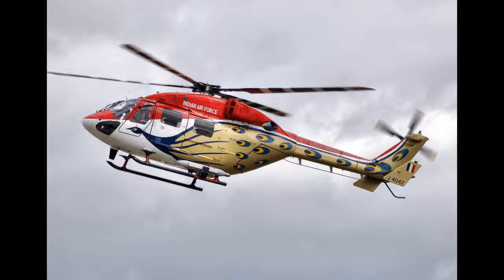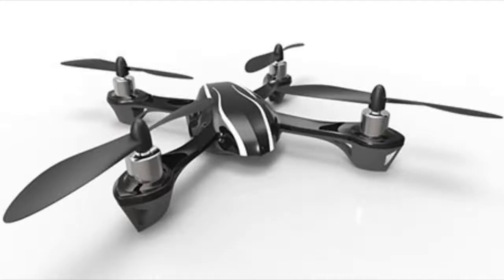The tail rotor of a conventional helicopter does not contribute to the lift and is therefore a point of inefficiency. In a quadcopter, there isn't this point of inefficiency, but having to continually slow down the speed of the props to remain in the air does waste a lot of energy. So a quadcopter is mechanically simpler, but less stable and efficient than a helicopter when scaling up the size.